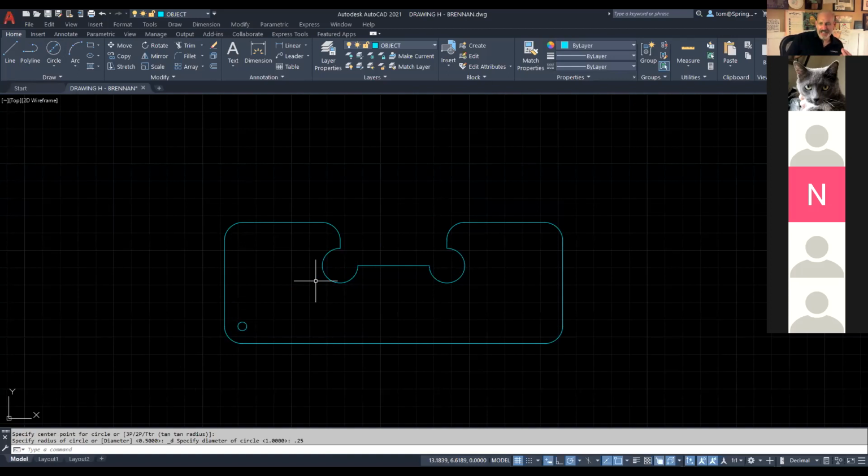So now I could either use the copy command and copy them around. I could do that, but I'll just show you how I do that. If I went to copy, the distance between these is all going to be 0.5. So I click here, I go here, and I can say, okay, 0.5, boom. Whoops. Try that again. 0.5, boom, like that. Okay, see that? And I could say 0.5, boom, like that. Oh, it went ahead and did another one. So I'll say 1, and then I'll say 1.5. Whoop, but I got off. Okay, see, this works, but it's kind of obnoxious, okay?